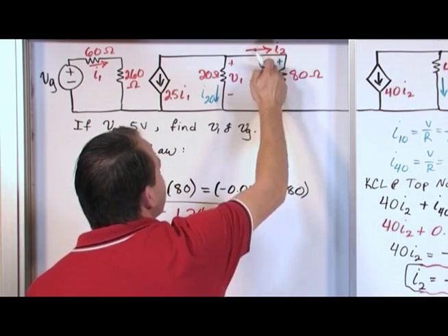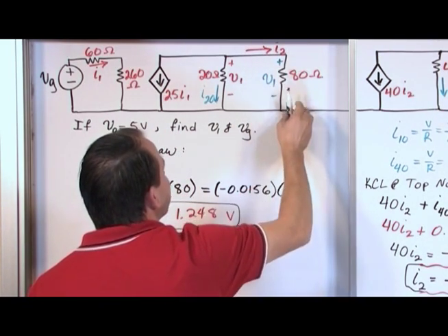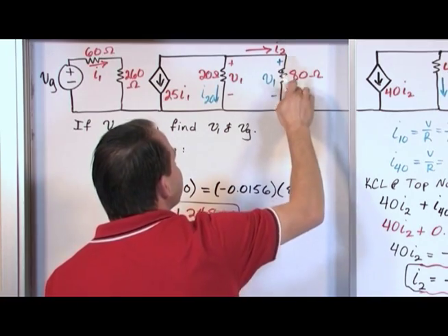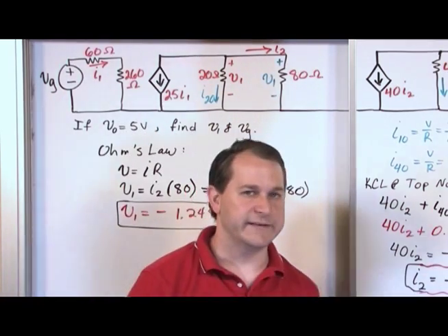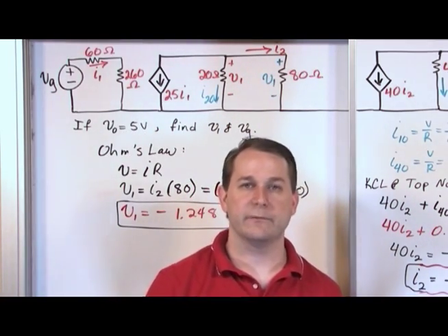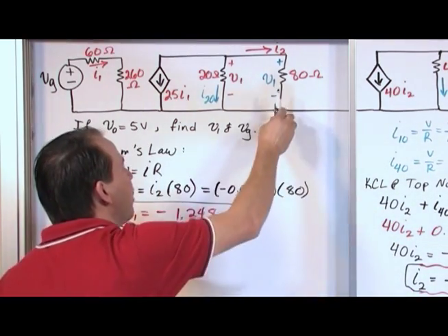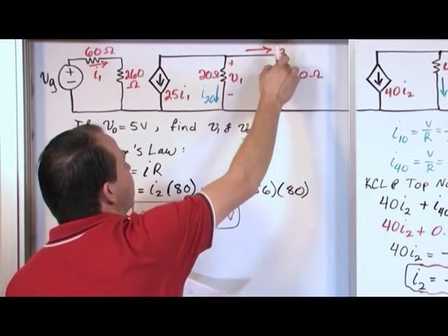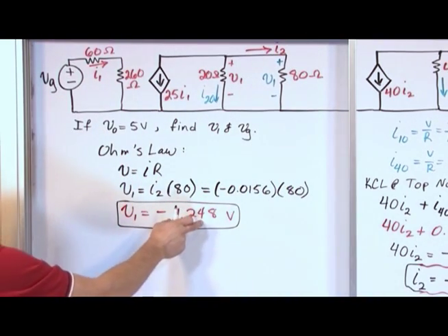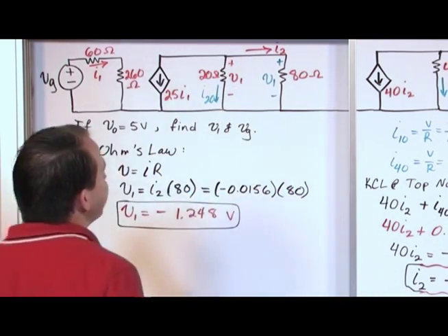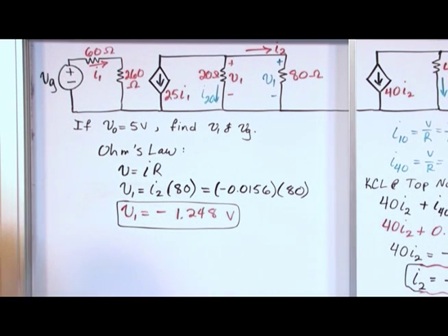And this voltage is not really like this, it's really positive to negative. So if current were flowing up, it would be positive, negative. So it's all self-consistent. We know that the voltage across a resistor should be in the direction of the current, positive to negative. So if the current were really flowing up, it should be positive to negative. So it makes sense that the voltage we get is backwards from what we draw here. So again, it's another sanity check.